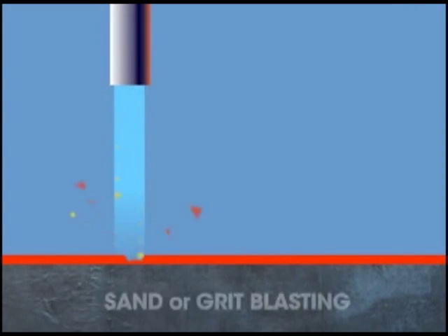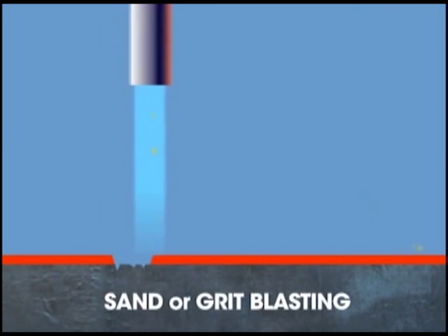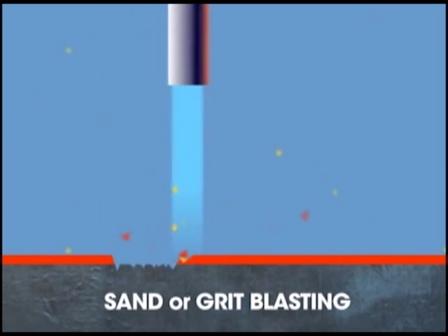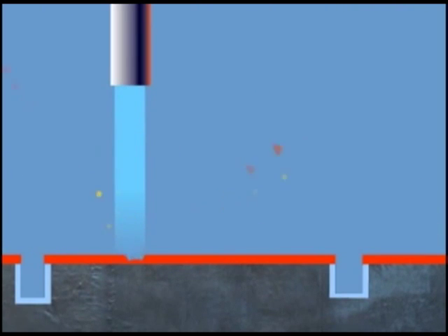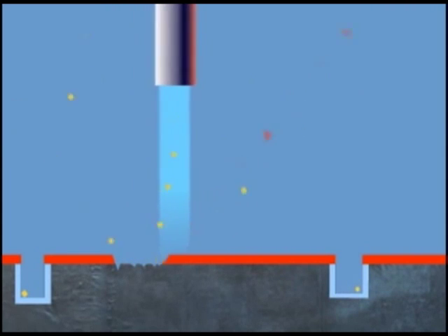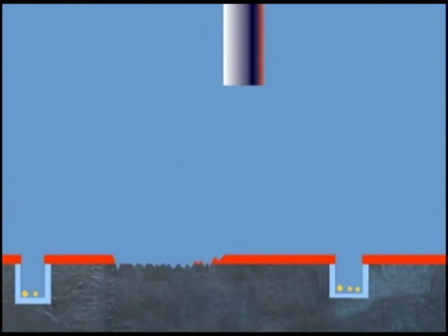Sandblasting is an abrasive process. Although it effectively removes surface contaminants, it also picks away at the substrate, wearing it away over time, altering surface geometries, destroying critical tolerances. Sand particles can also become entrapped, causing critical problems that can shut down the manufacturing process while the problem is solved.